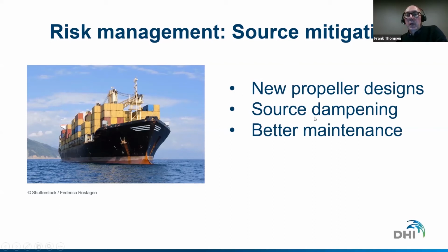You can also use source dampening for pile driving. For example, you can put caps on the pile driver. It's not done very often right now. This is historical stuff, basically, but it's an option. And basically, through better maintenance, you can reduce the noise levels quite considerably. This is known from, for example, dredging.